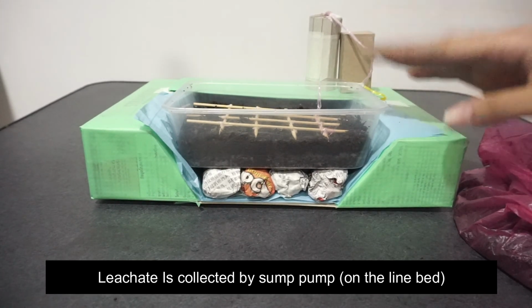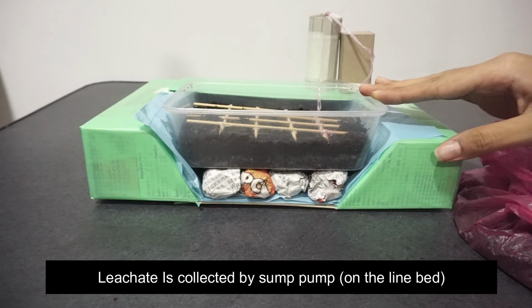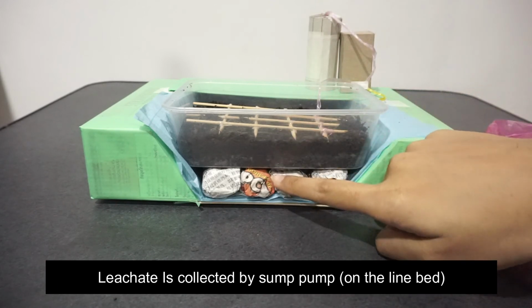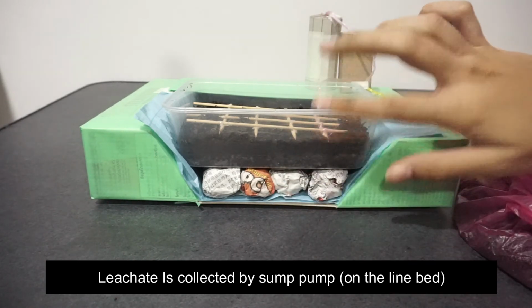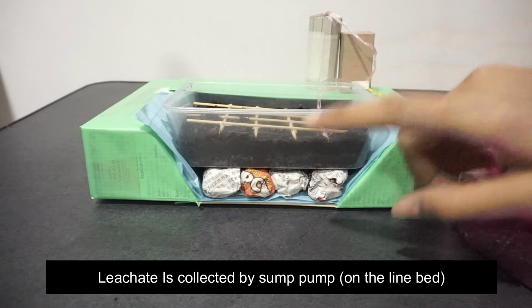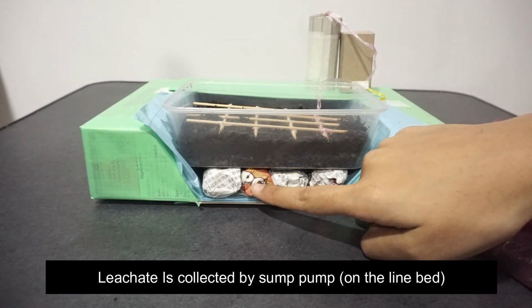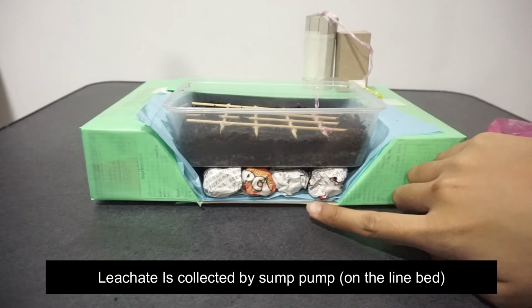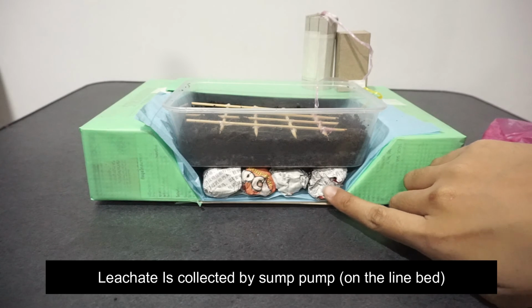The release of the leachate occurs, and it is collected by a sump pump underneath the soil layer, in the drainage layer, which is this sand layer.